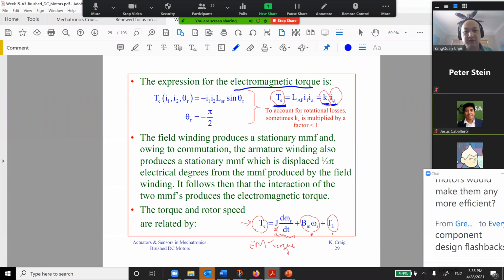So with that, this is my winding, this is my armature, and the link to my load, okay? So then this has to satisfy Newton's second law, meaning this is the load torque from the load. This is the torque I'm providing to you, and this is my electromagnetic torque. This is J, from Newton's second law, right? Moment of inertia times angular acceleration.